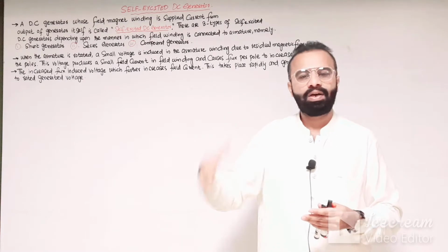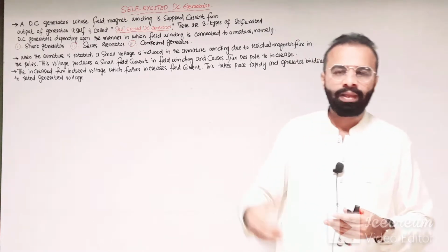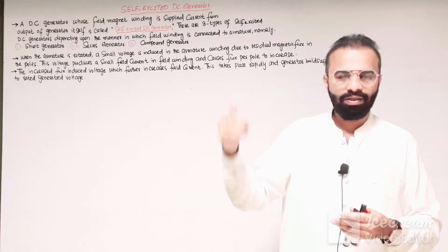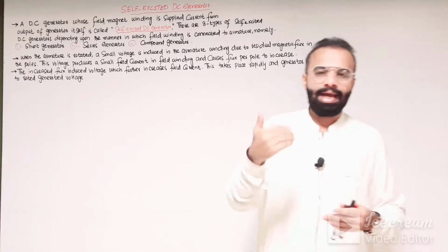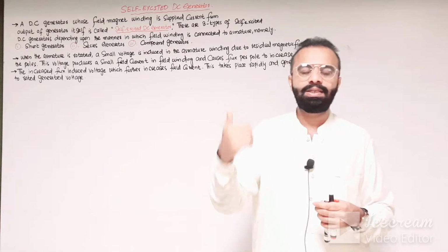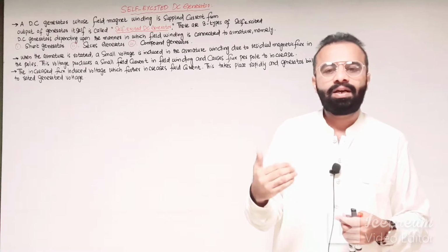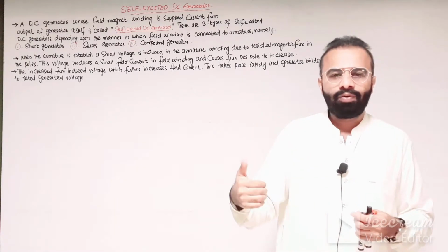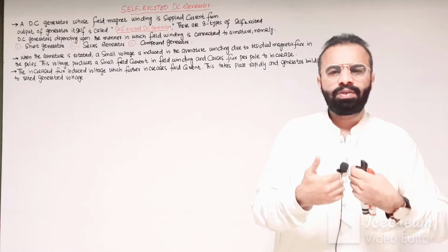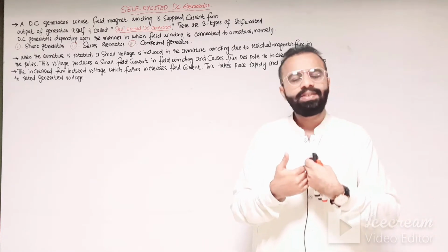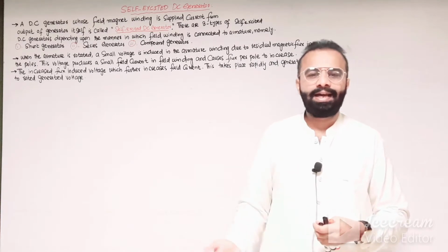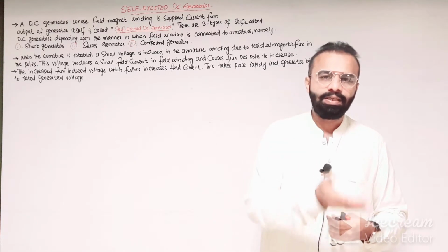According to Faraday's law of electromagnetic induction, whenever the flux linking with a coil changes, an EMF is induced in the armature conductors. In the armature winding the induced voltage is always AC, so we connect an assembly to the same shaft as the armature core, which is the commutator, a mechanical rectifier which converts the AC voltage into DC voltage.